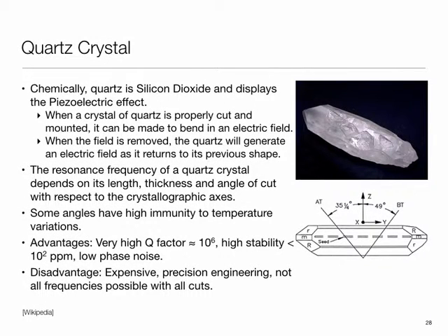So that brings us to quartz crystal, which is the dominating technology currently, although MEMS is trying to catch up. Basically what happens is you can cut the crystal along one of its planes, and the idea is that you can apply a voltage to it, start mechanical oscillation, mechanical vibration, so to say, and then in turn it begins to amplify your signal. So it resonates at a given frequency, which is driven by the mechanical characteristics, and then you use some amplifier circuit to extract that out.